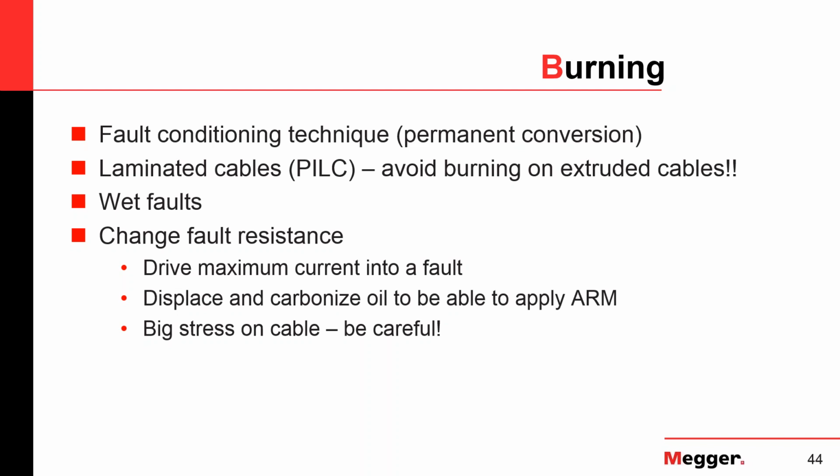And if you're lucky, you create a situation where your TDR can pick it up, or where you have the chance of thumping. But where do you stop? You don't know where to stop. So in most of the cases, when people try to burn plastic cables, they literally burn it to death. They burn it open. They carbonize it into a condition where it's really hard then to go on with actual fault location. So be very careful with burning.